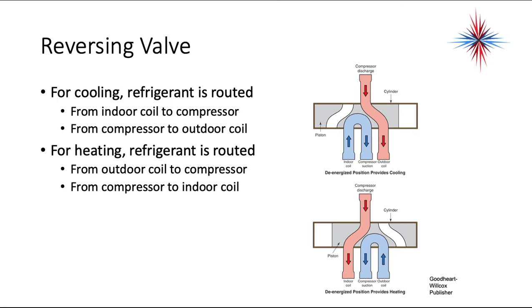So just always be aware that if the reversing valve is energized, is it cooling or heating? If you start a system up and you have your thermostat set for cooling and the condenser or the outdoor unit is blowing cold air, it means that you have to change the position of that reversing valve wire.